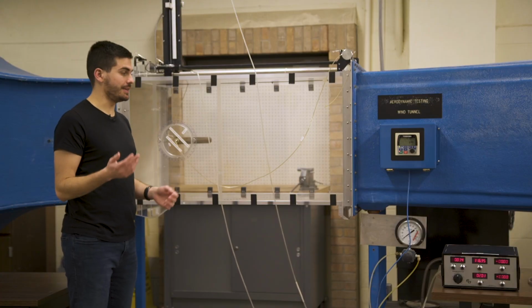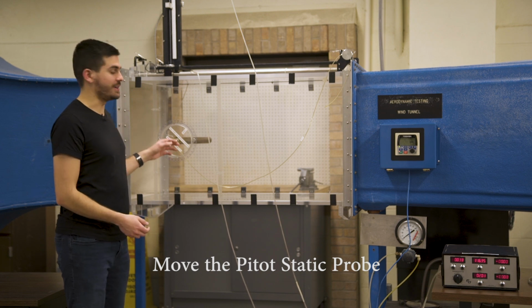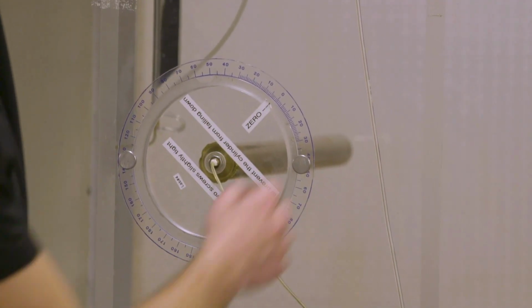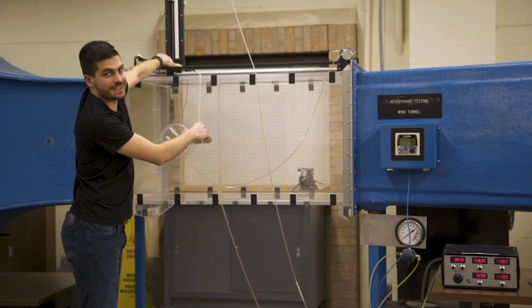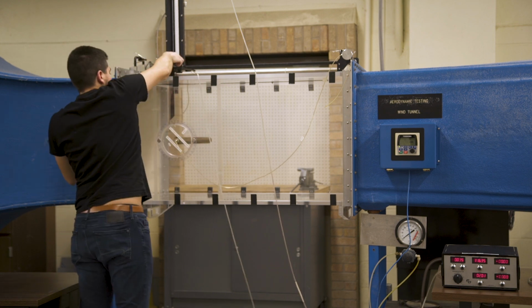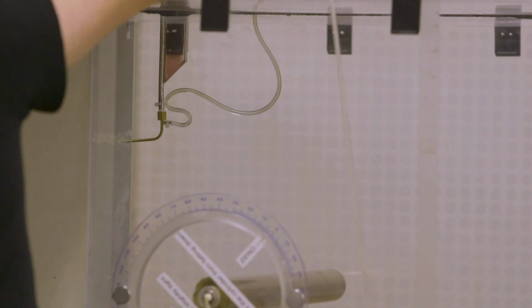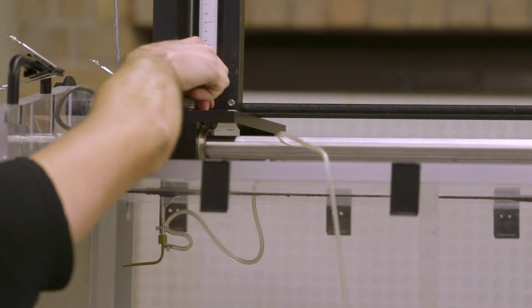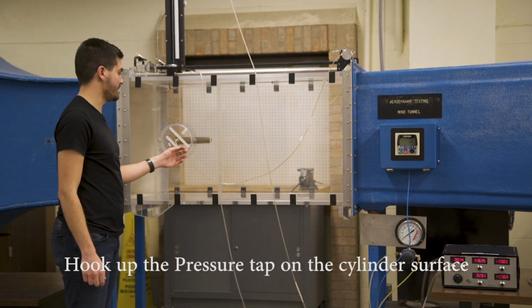After we set up the correct wind tunnel speed, we'll need to move our pitot-static probe out of the way so as not to affect the flow around the cylinder. So what I'm going to do is just traverse this up and out of the way so that it's not upstream of the cylinder anymore. It's going to take a while. To be safe, you can just move it as far away as you can. And now we're ready to hook up the pressure tap on the cylinder surface.